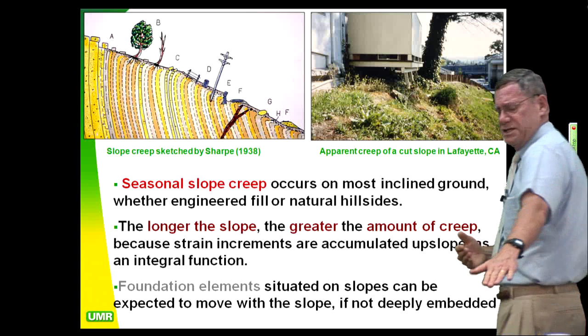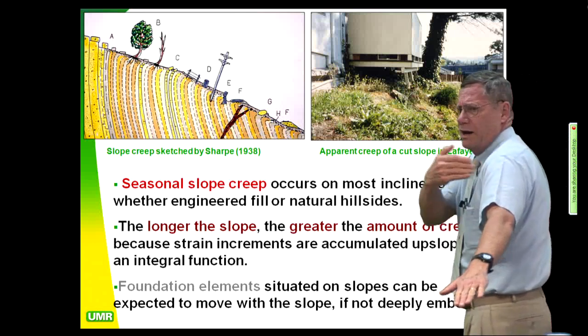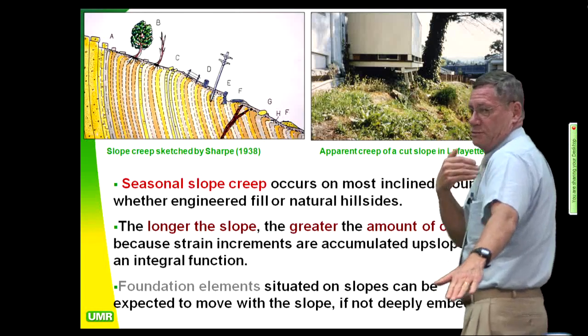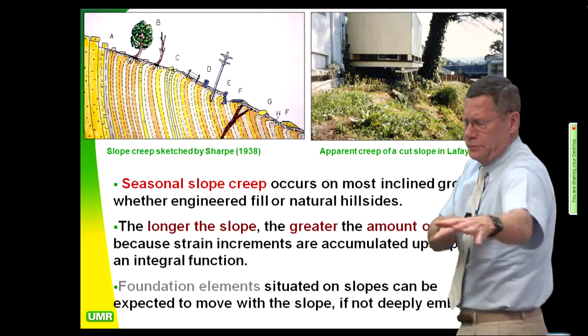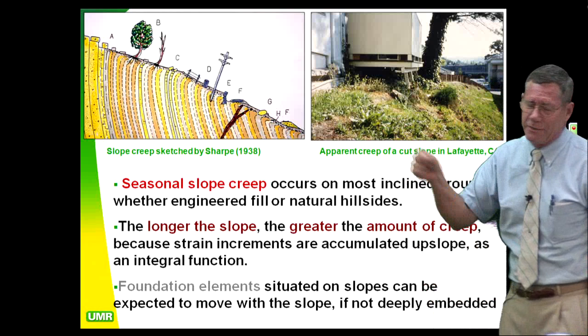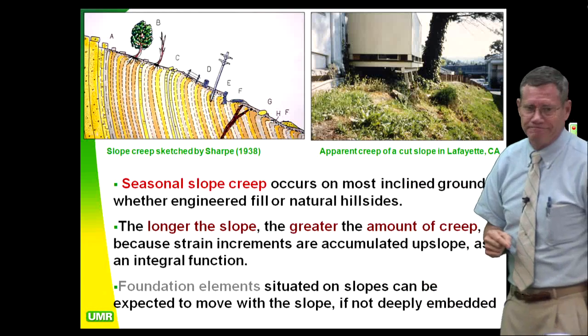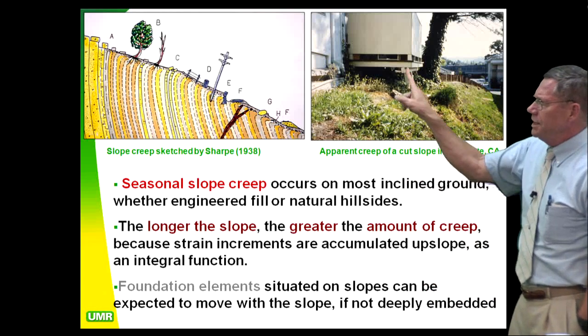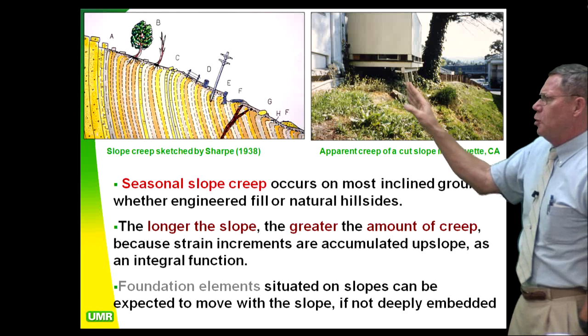You have a long descending slope, get your butt away from it. Don't put your structure right out there on it. You're going to be in the influence area of that slope. Just draw a free body diagram, and you'll see. Okay. Here's a typical slope creep problem.